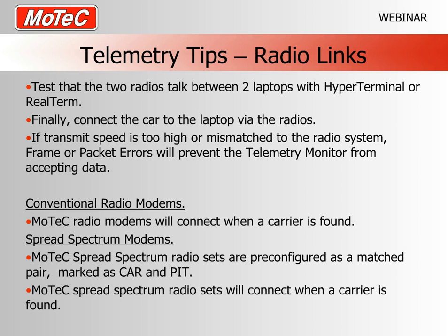Okay, so the next thing we want to do is we will test that the two radio links talk to each other just using a data transmission terminal program. So I'm going to show you one of those a little bit later, but there are a few options here with the PC. Virtually all PCs have a program called Hyperterminal, which is just part of the normal operating system, and there's also a program called RealTerm that we also suggest.